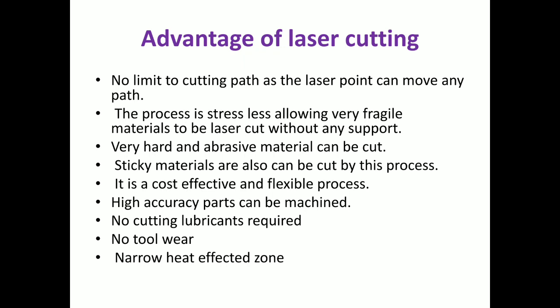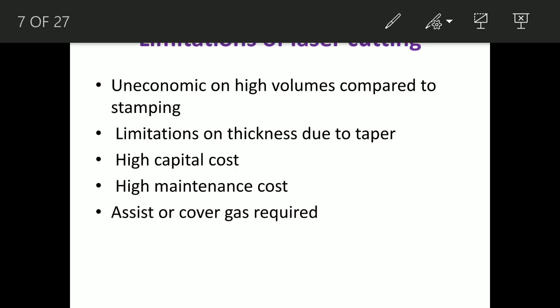There is a very narrow heat affected zone, as compared to if we do gas cutting, where there is a huge amount of heat affected zone. Very high width of heat affected zone is there, which is not desirable in any process.